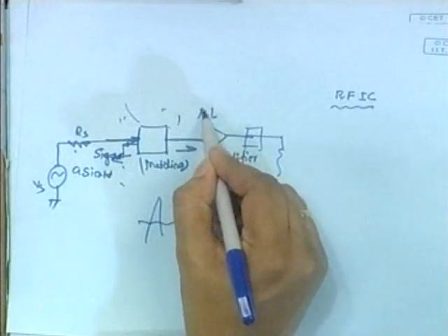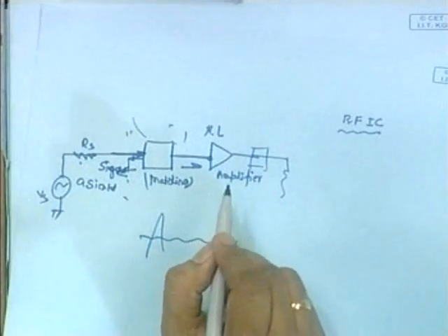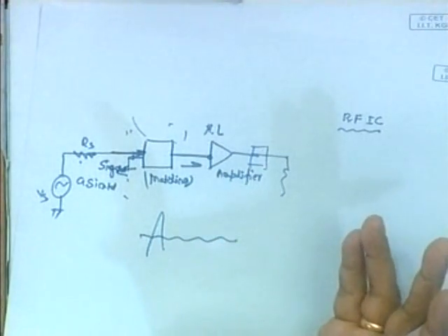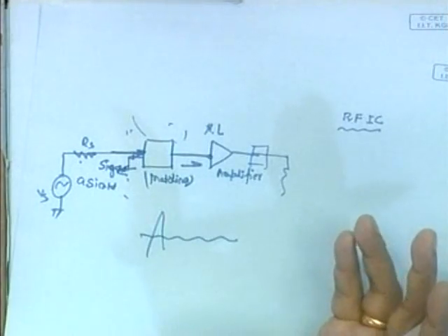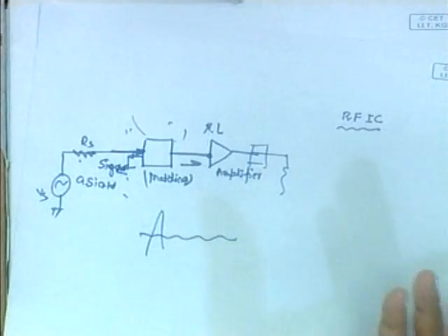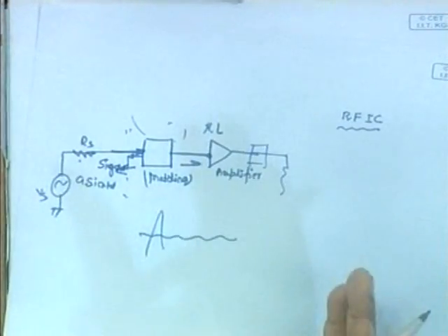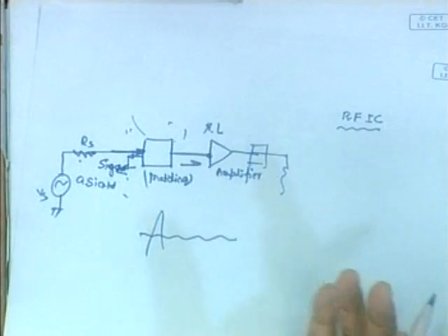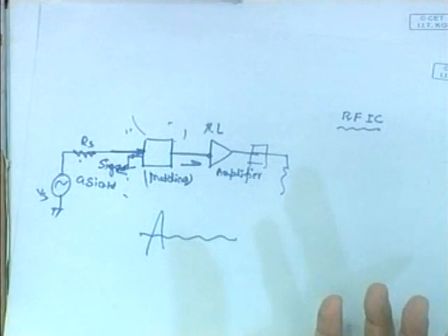Then another term is called the dynamic range. Dynamic range means what is the maximum signal you can detect, ensuring the linearity of the system. Suppose signal strength is very high and reaches its nonlinear region, then what will happen? In spite of frequency omega, you will get all other harmonics, because any nonlinear device, when a signal is passed through, generates other frequencies too. That is simply a wastage of power, and they will intermodulate and create a lot of spurious noise interference to your actual signals.